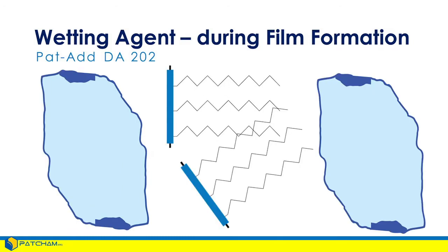And so as these pigment particles come close together, the physical spacing that the wetting agent, the A202, provides is greater than the coiled up APE type wetting agents, providing greater molecular spacing between the particles to help prevent the flocculation of these two particles.